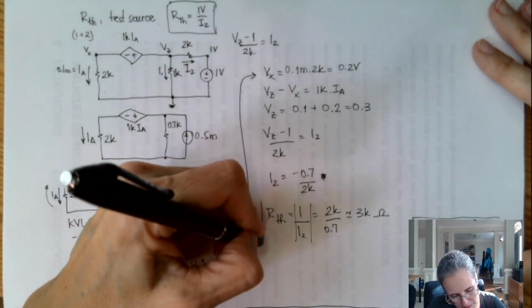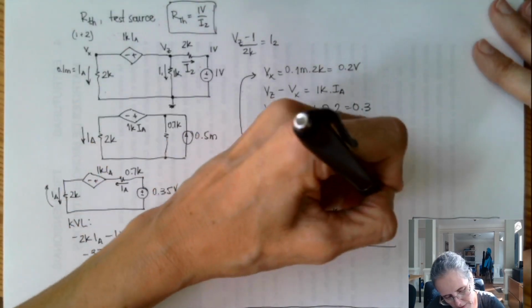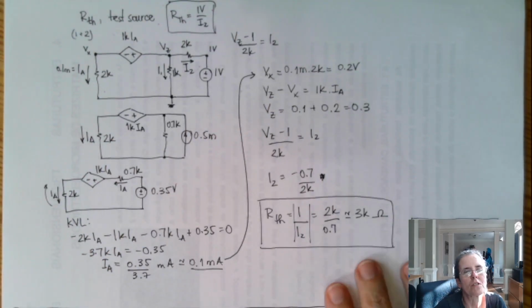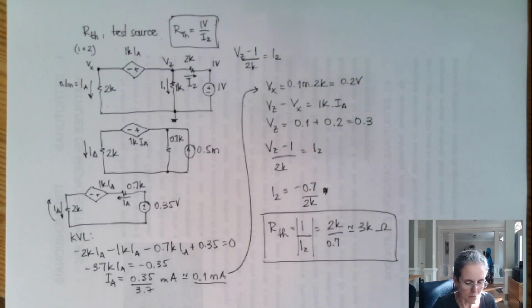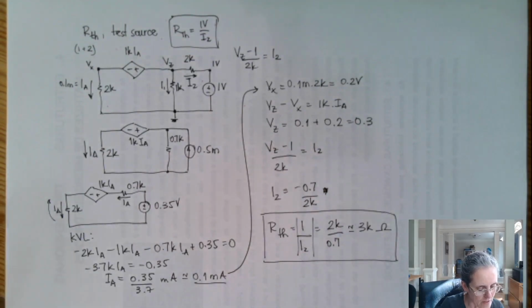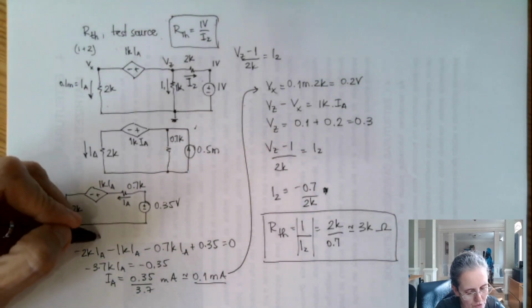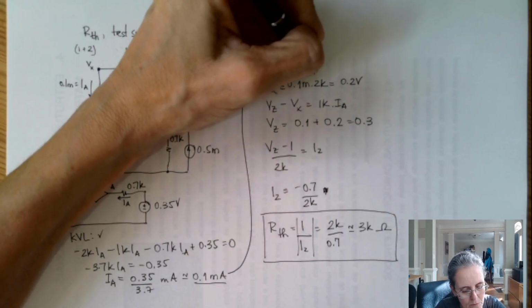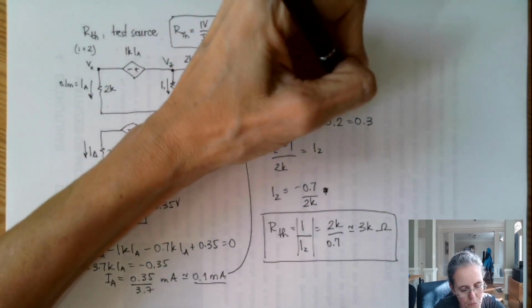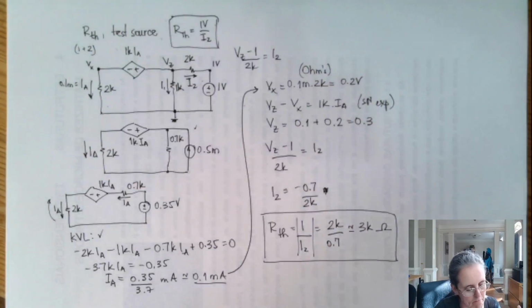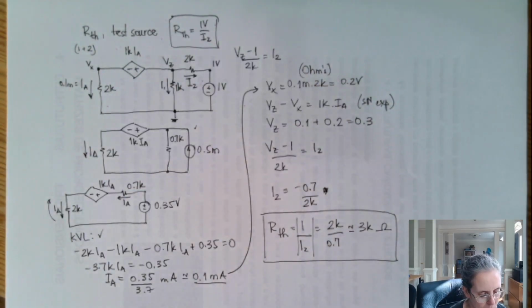So that's what I expect on the exam, for you to find the Rthevenin. It's very approximate, so chances are there won't be exact numbers, and chances are everybody's going to have different numbers. I'm more interested in seeing if you know how to use source transformation, KVL, Ohm's law, supernode expression, you know, circuit resistors in series and in parallel.